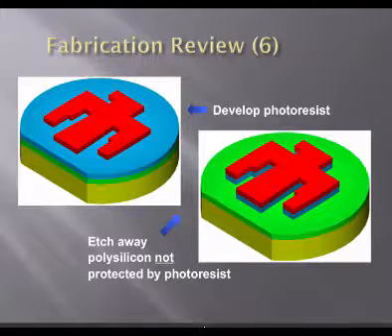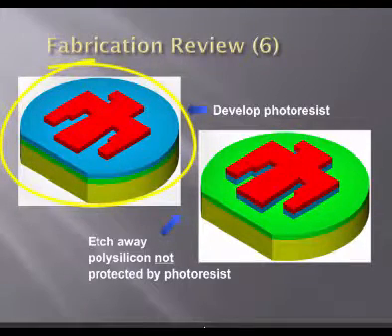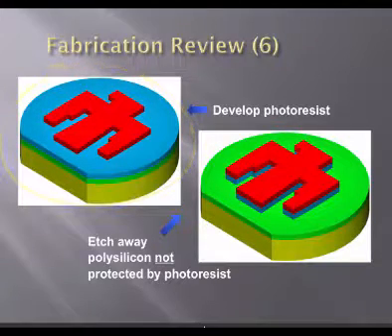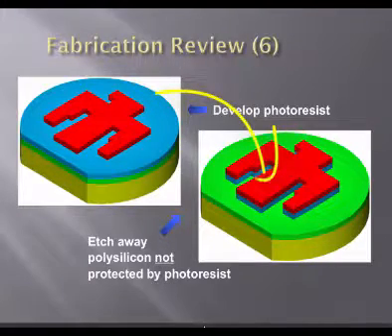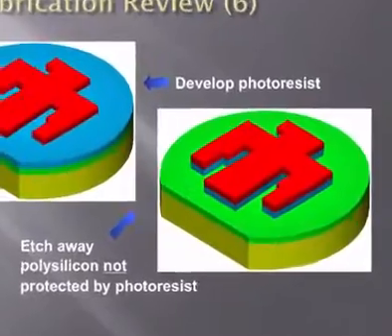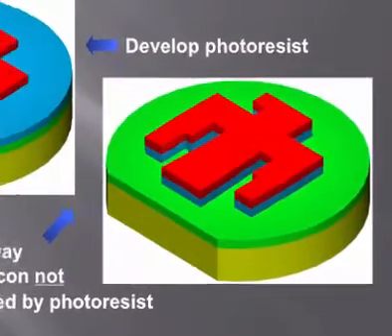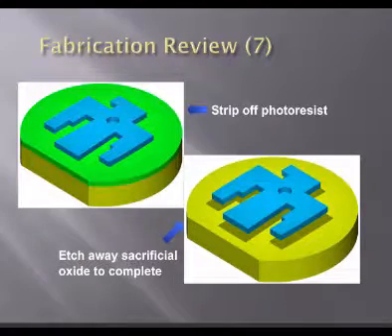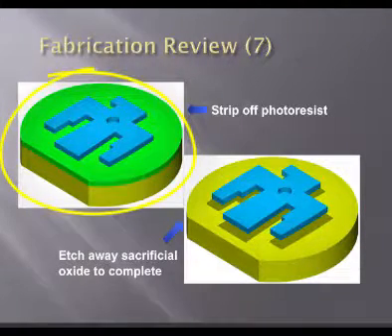So now this upper left picture shows the photoresist image on top of the, what is that blue stuff? The blue layer was what? Polysilicon, right? So we're going to protect where the photoresist is, so everything else will get etched away, and that's what the next part's depicted, right? After you etch the polycrystalline silicon, you still have photoresist on top, and we have to get rid of that. All right, so we strip the resist off,